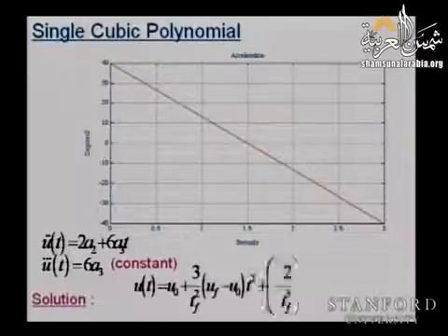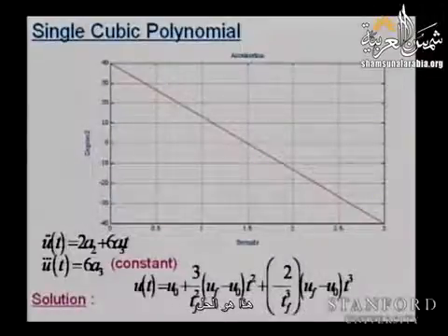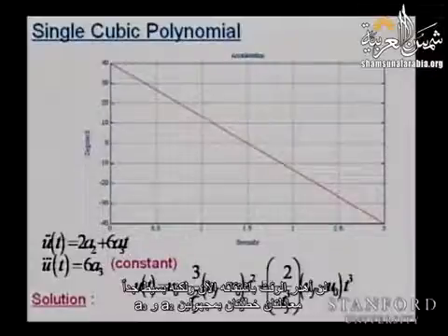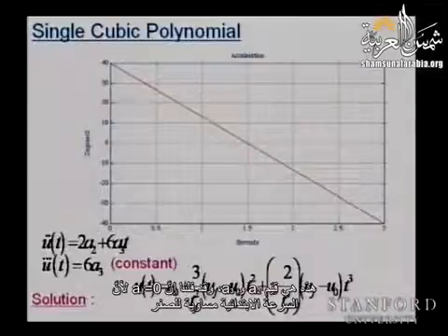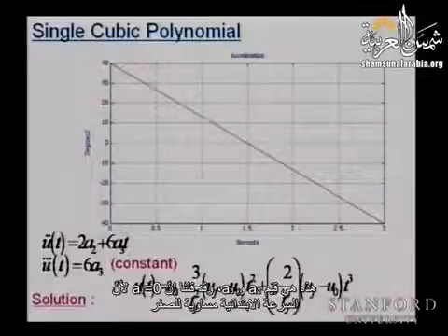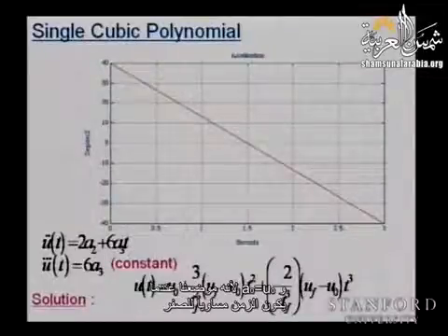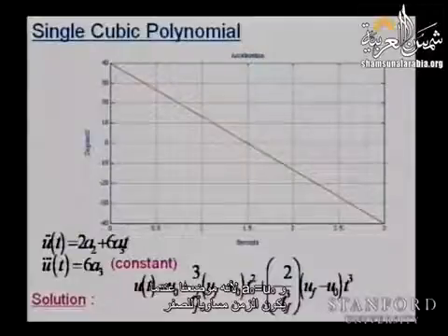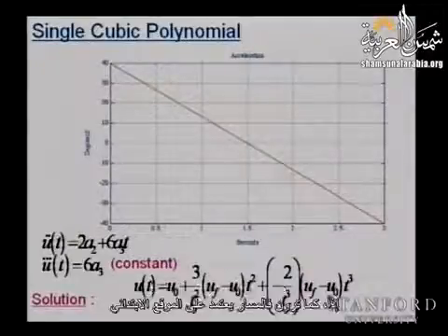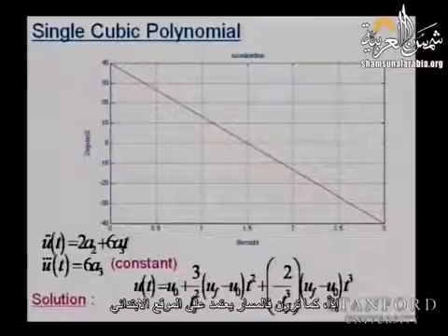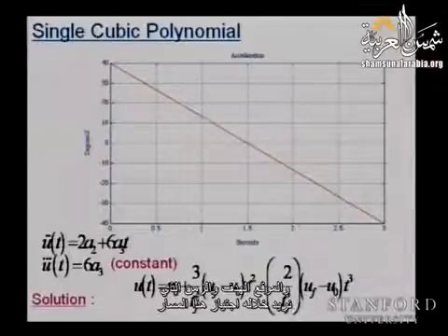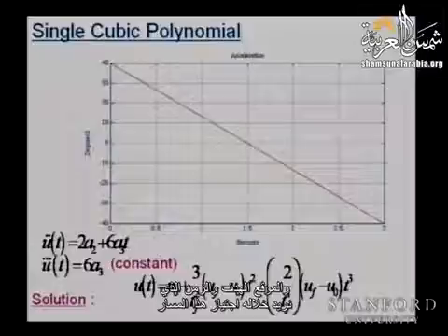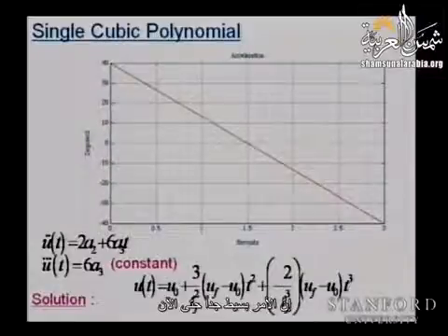So basically, here is the solution. I'm not going to spend the time to derive it right now, but it's pretty simple. Two linear equations with two unknowns, a2 and a3. These are the values of a2 and a3. a1 we set as 0 because the velocity at the beginning is 0, and a0 is u0 because that's the position at time 0. So as you can see, the trajectory depends on the initial position, goal position, and the time that we want to traverse that segment. Okay? Pretty simple so far.